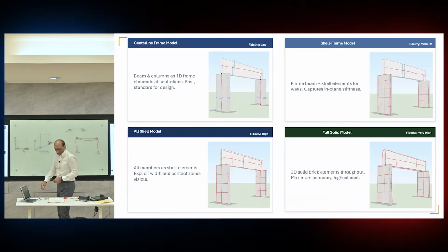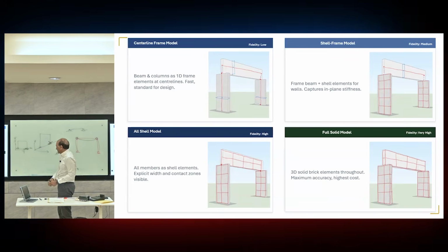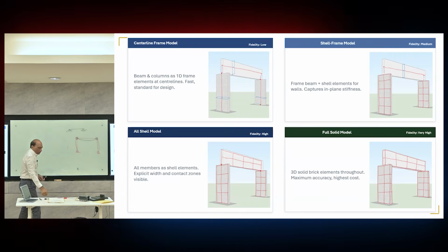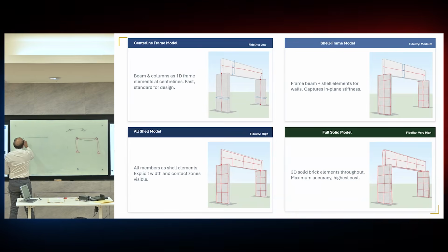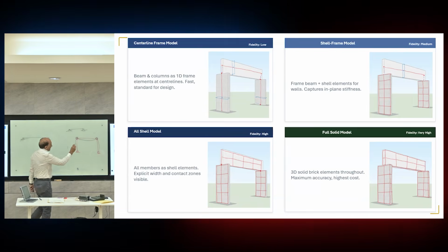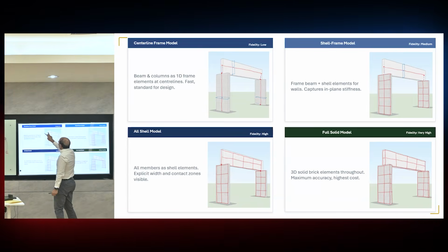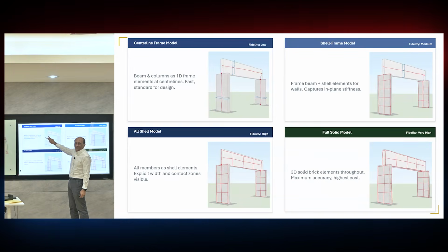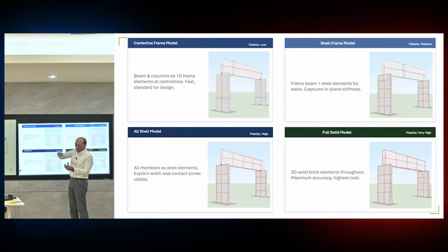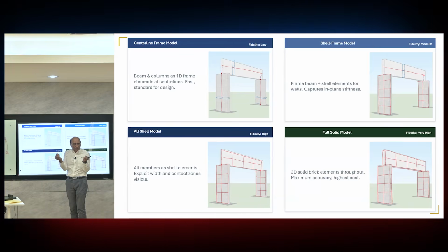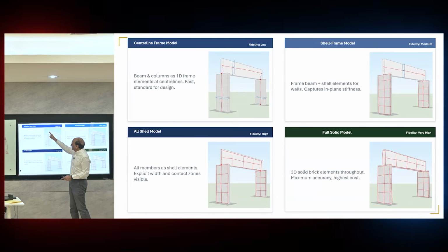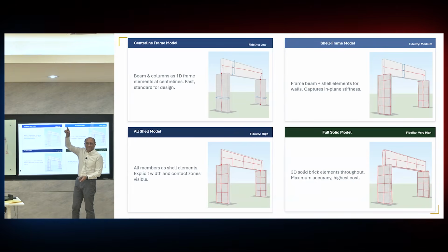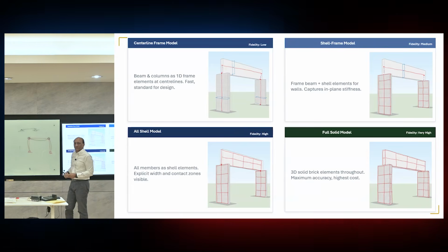Please watch this carefully because it's a very, very important point. You might want to say, okay, I'm going to model this beam like this and apply the load. That is the beam over there. But your supports will be here and here, not where the actual wall is resting, because your supports are at the ends of the beam. But the beam is connected at the bottom of the beam. So you are just missing that whole offset of the beam.